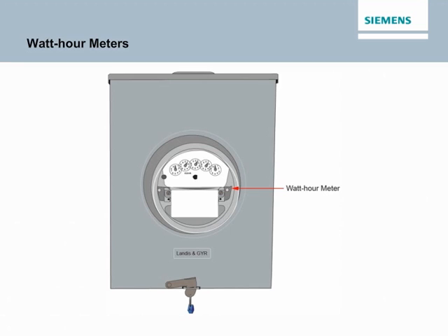Residential applications often use a watt-hour meter designed as self-contained. A self-contained meter is directly connected to the power source and the load. Watt-hour meters designated as transformer rated, or TR, use current transformers, CTs, and voltage transformers, also called potential transformers or PTs. These reduce the energy applied to the meter. TR meters are common in commercial applications because of the higher load current required for these applications.